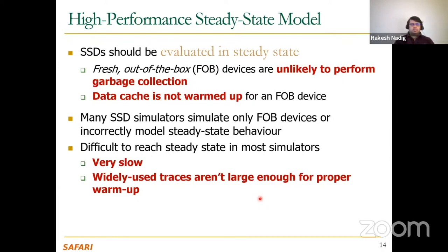So that is the reason why it's very critical to evaluate the SSD in a steady state, where garbage collection is getting triggered and the data cache has a lot of entries. There are also some workloads which can end up thrashing the data cache, which is also a critical behavior in which the SSD has to be evaluated.